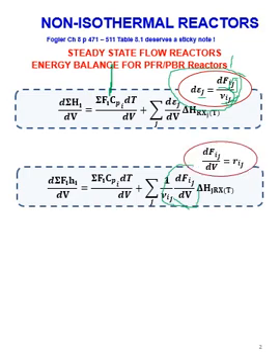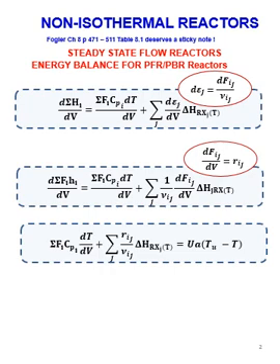And if we now inspect that, we realize that this dF_ij/dV term is simply equal to the rate at which component i participates in reaction j. So for each of the reactions, I need to consider a single rate term and divide by the stoichiometric coefficient of the specific component that I used as the basis to perform my energy balance. So after substitution, and this is the shape that you used in that extensive tutorial where we had multiple reactions, we had to account for each heat of reaction.